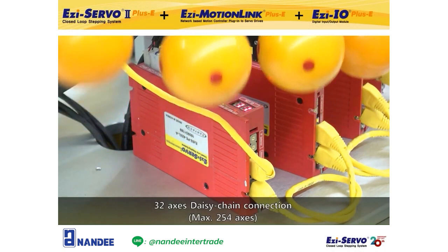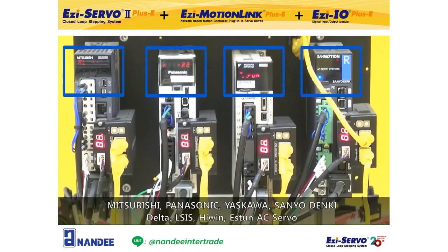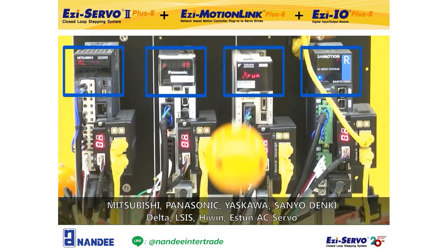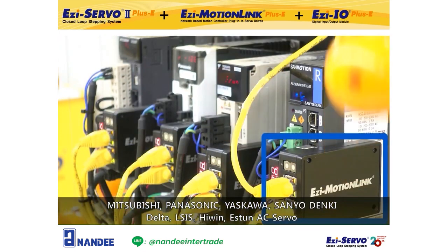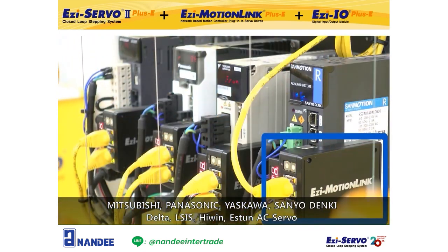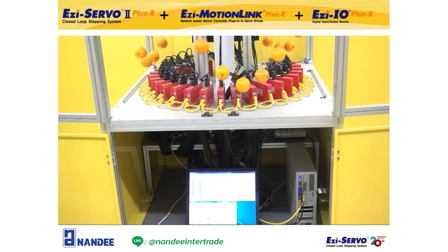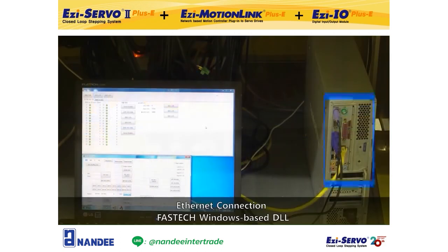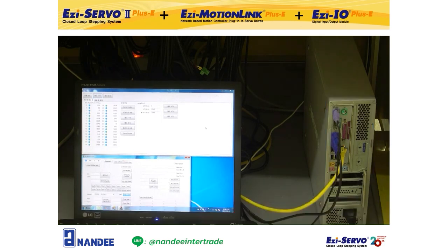By applying EZ motion link to AC servo such as Mitsubishi, Panasonic, Yaskawa, and Sanyo, a total 32 axes including EZ Servo 2 plus E and AC servo were controlled at the same time. As you can see, AC servo and EZ servo are controlled by one network and program. There is no need for a separate motion board and can be operated simply with a PC.